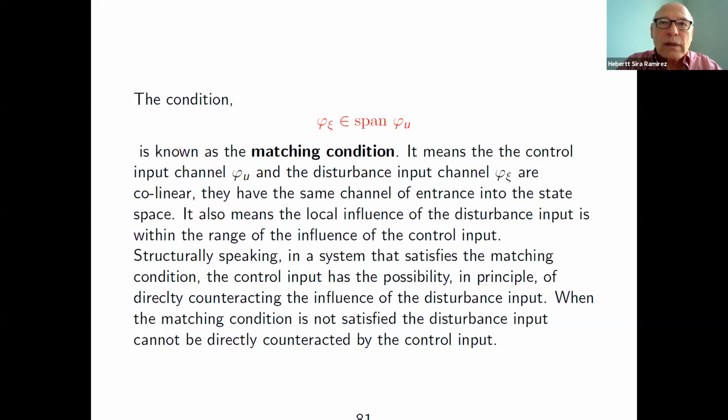The electrical torque and the mechanical torque, under the same system of units, are numerically equal. The mechanical equation has the torque constant multiplying the armature current, and the electrical part has the same constant in special units multiplying the angular velocity.